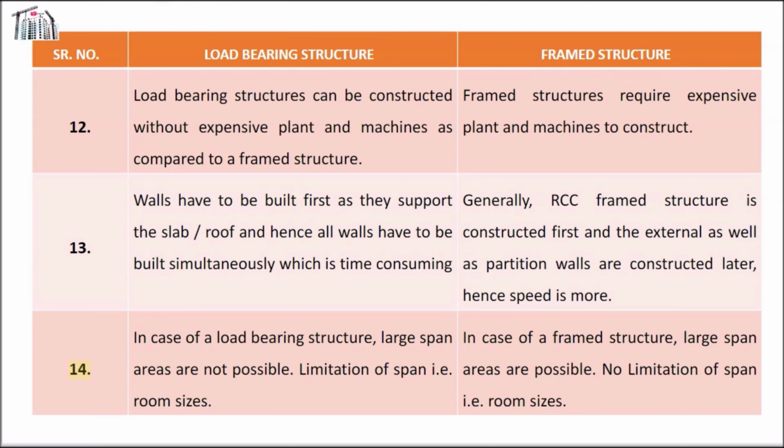14. In case of a load-bearing structure, large span areas are not possible. Limitation of span, i.e. room sizes. In case of a framed structure, large span areas are possible. No limitation of span, i.e. room sizes.